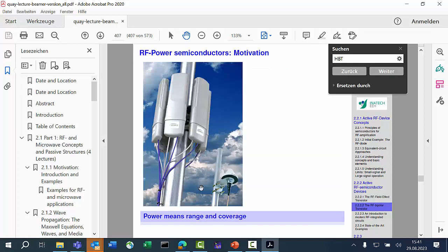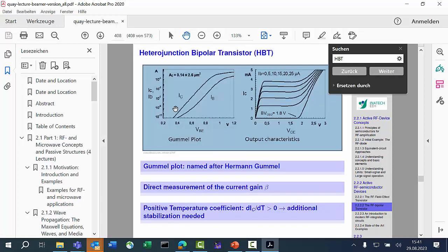Yeah. And what we are trying to do here is we want to send as much carriers in the positive direction that they go from the emitter to the collector. But we have to make sure that the control current, the one which controls us, is low. Yeah? If we now have a high concentration of base holes, then this current will also go up. But that's stupid because the ratio of the controlled current by the control current is getting worse.